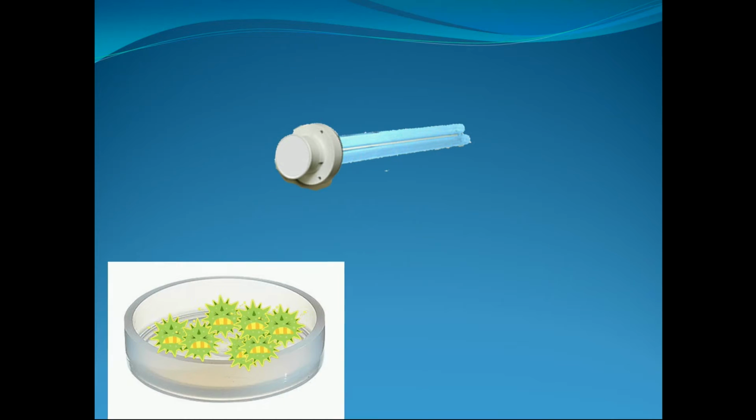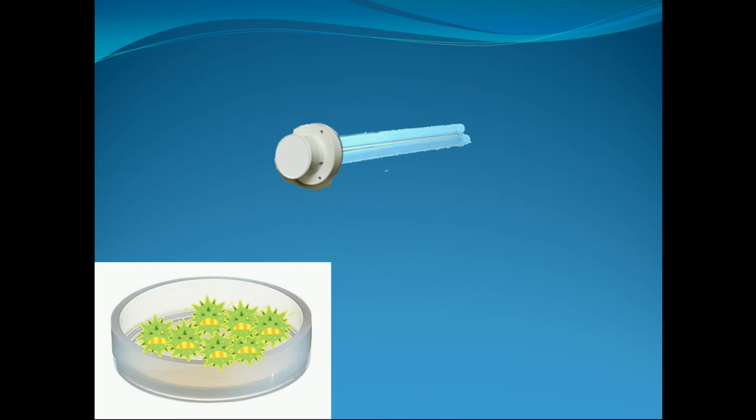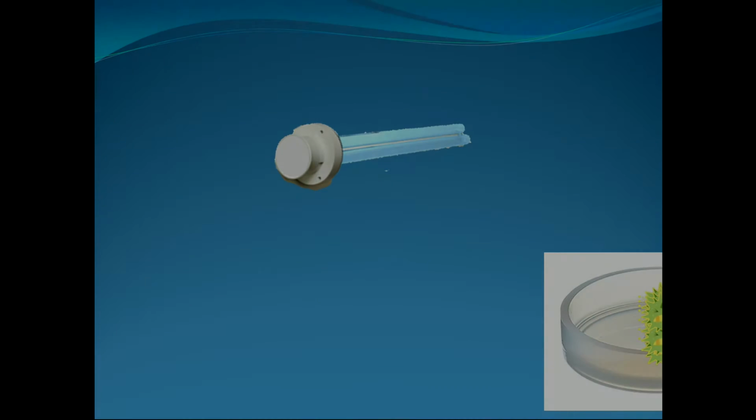Now if I take that same petri dish and zing it by like a frisbee at 400 feet per minute, like it's going by through ductwork, the light doesn't have enough power to kill stuff as it's going by real fast. So you've got a lack of dwell time. It doesn't have the same amount of time to shine on there to truly have an effect. Right. So to get the right kill or the right sterilization, because UV light doesn't kill a lot when stuff's airborne, it has to get anywhere from 2 to 6 inches from the lamp, depending on what power you're using, in order for it to die.